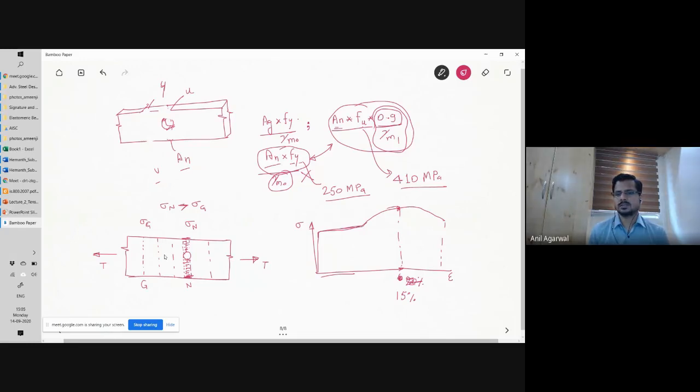So as soon as the stresses start to strain harden here, the yielding will happen here also. There is no special preference why this yielding should happen only here and not here and not here and not here. And that yielding can actually take place over the entire length of the member. Correct? And of course, after some point, there will be some necking and so on, and those things will make the yielding more concentrated. But still, if you imagine the amount of length change that you will get as a result of yielding here will be, if let's say yielding is at least distributed over the width of the member.